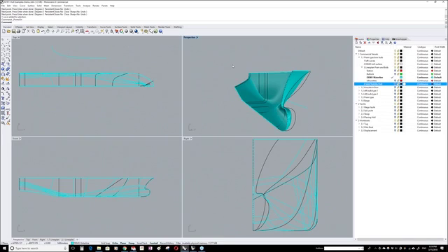Gerard. Yeah, I can tell a little more about this. What I found out is that when I learned this technique myself, I also wanted my surface to run through specific points. And it took me quite some time to accept the fact that control points of a surface are not always on the surface. And in this approach, the loft curves are also not always touching the surface. But what I see is that also in other hull fairing software, when you turn on control points of the surface, they will also not touch your surface.